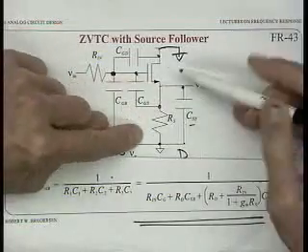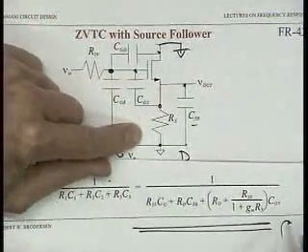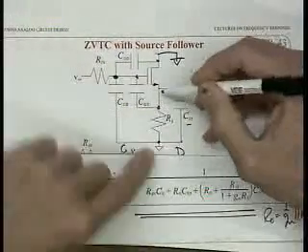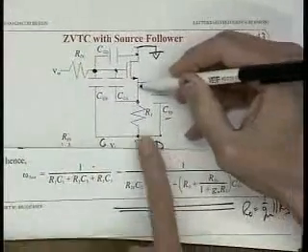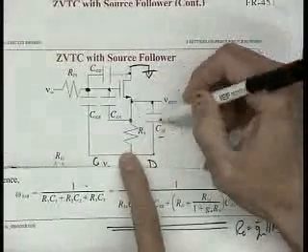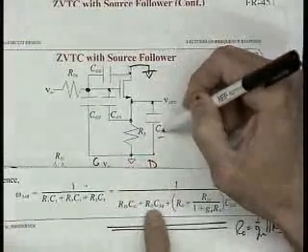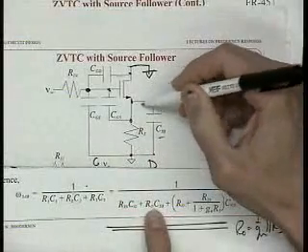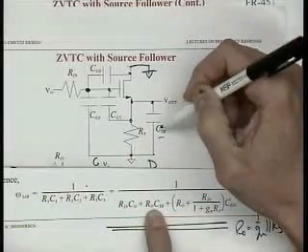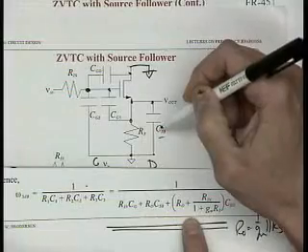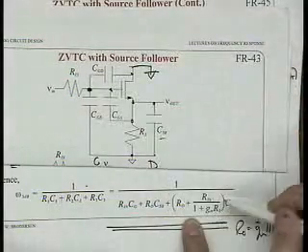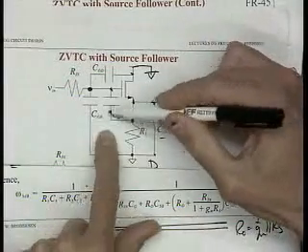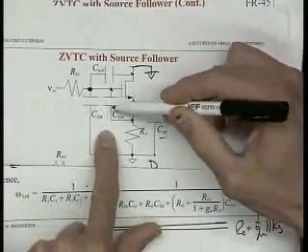The R out was equal to, remember, 1 over Gm in parallel with Rs. So that's kind of the capacitance on the output here. So it's the resistance on this node, and you see CSB. So it's 1 over Gm looking up and Rs down in parallel with it with CSB. So that's that time constant. And this third one here we just calculated is R0 times CGS. So that's a little bit like the output resistance driving CGS.